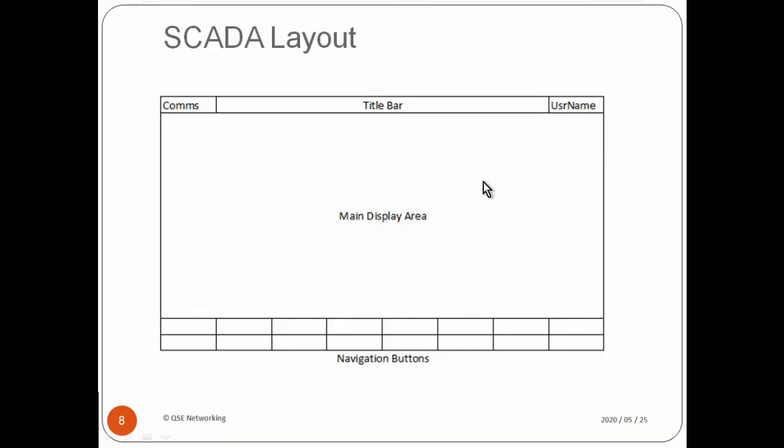Now this can be, I'll give you a warning. You don't want people to see the menu bar because they can start to fiddle and halt logic and reinitialize IO, and they can go to the development even if you've closed it. So we want to hide the menu bar. And also if I go and minimize the screen, then the guy's not actually watching the screen, so he doesn't know that there's anything wrong. So we want to make sure that this graphic almost can't be changed. So literally he's got no navigation away in Windows to go somewhere else. So we want to hide the title bar and we want to hide the menu bar.